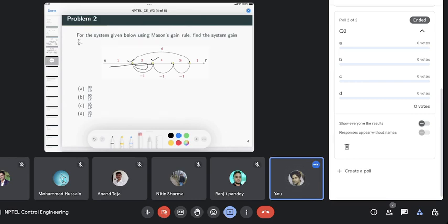So you just see if you can go from this R to Y, between which you want to find the transfer function, without traveling any node more than once. So one path will be straight, this one, and another path is through this. Other paths will travel a node more than once, right? So these are not forward paths other than these. So you have only two forward paths.